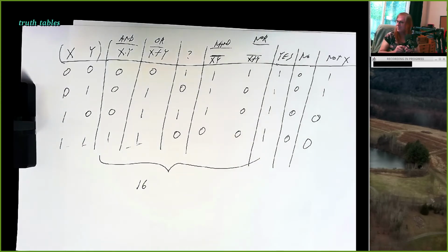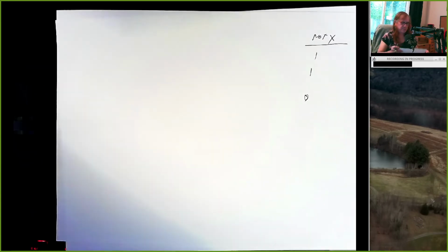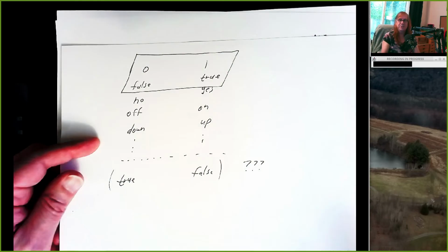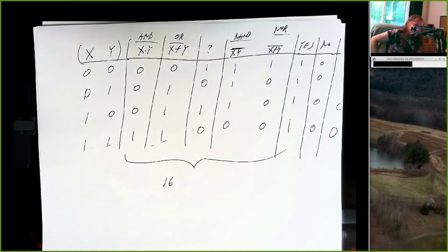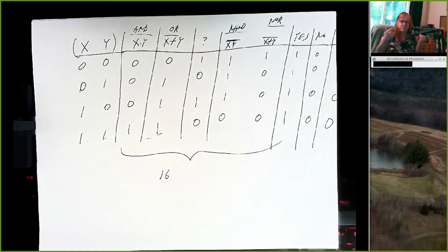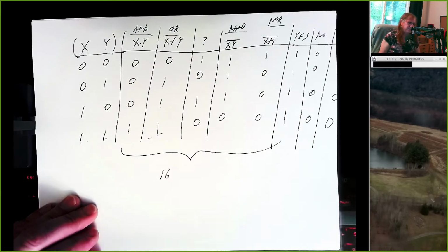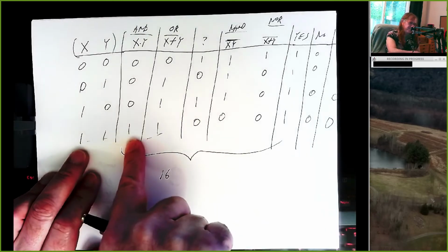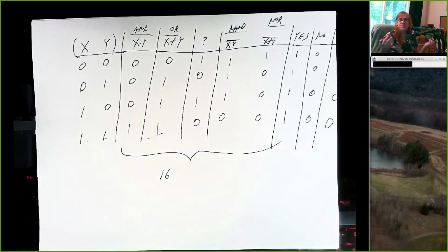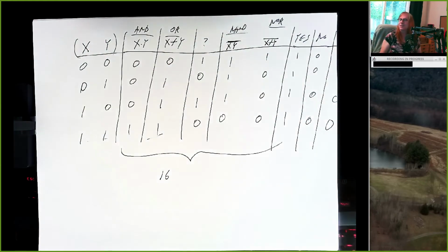And they're named truth tables because we think of these things 0 and 1 as being true or false, having a truth value, and it's literally a table of truth values. And so as we work with different ways to operate on variables, we can describe, if both of these are a 1, then the output should be a 1, otherwise it should be a 0. We can make descriptions like that in words, but we can also just write a truth table to describe exactly how some function operates on its inputs.